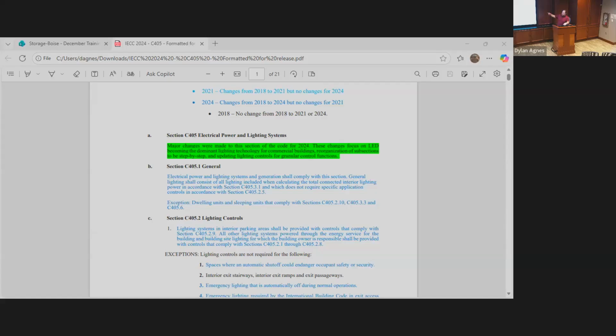And so for zone 1, you're going from 350 watts to 160 if you have to comply with 2024. So you still have to provide lumens, you're just now forced to do it using fewer watts. So you have to be more strategic about where you place your lights, as well as the type of light you select. It also basically forces your hand to use only LEDs.